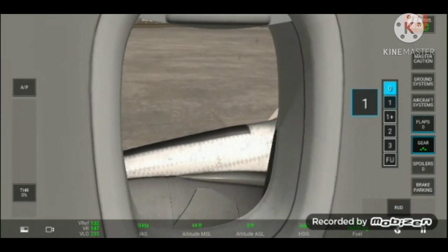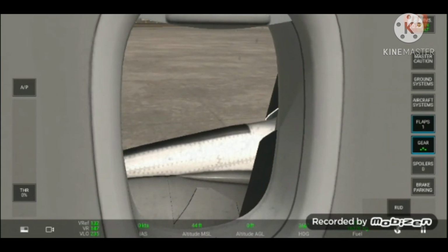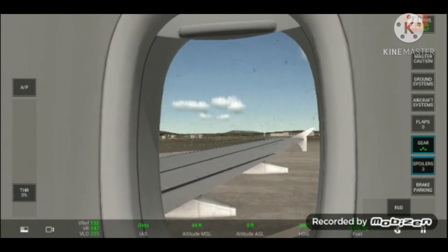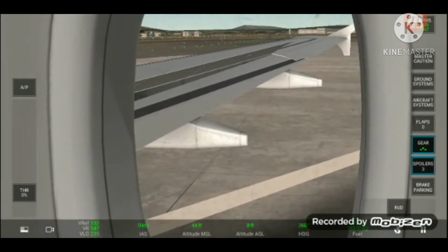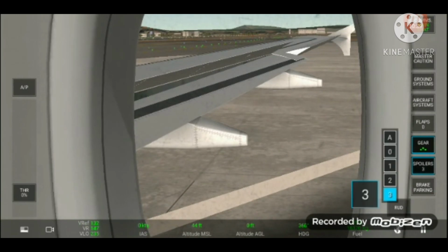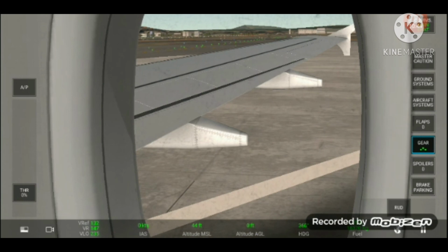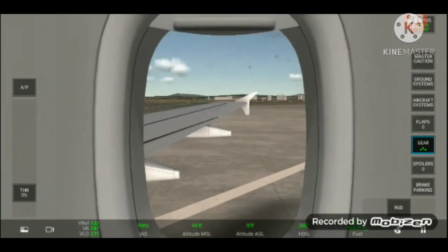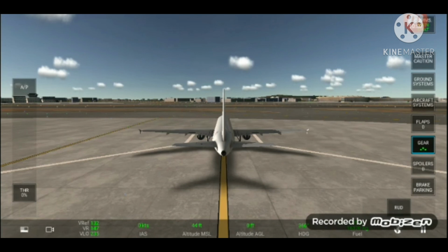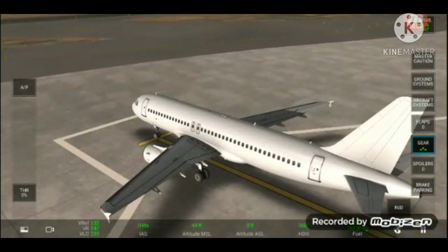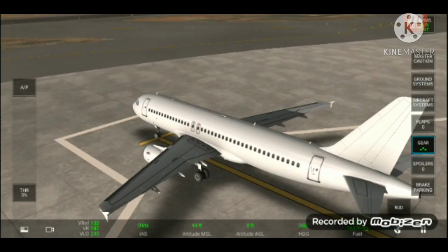Now, finally, air brakes. Air brakes are used to increase drag. Spoilers might act as air brakes, but are not pure brakes, as they function as lift dumpers or in some cases as roll control surfaces. Air brakes are surfaces that deflect outwards from the fuselage, in most cases symmetrically on opposite sides, into the airstream in order to increase form drag, as they are in most cases located elsewhere on the aircraft, so they do not directly affect the lift generated by the wing.